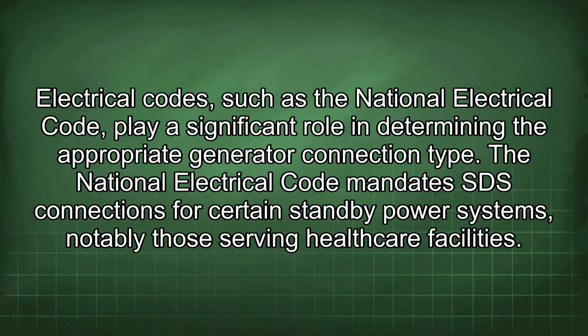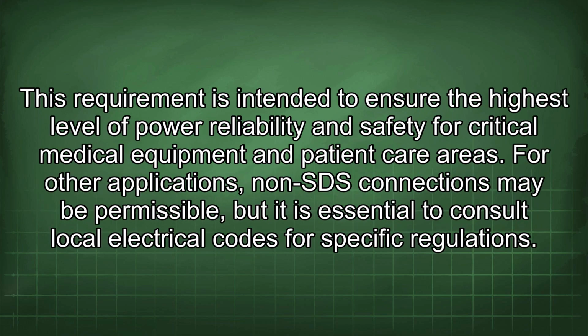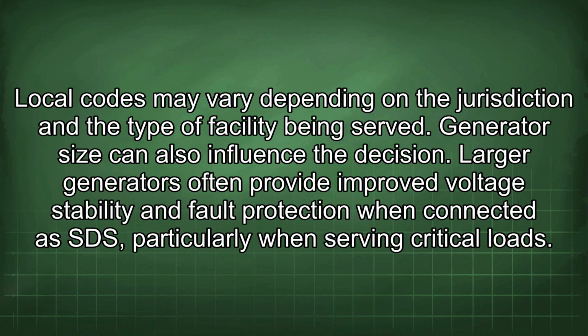Electrical codes, such as the National Electrical Code, play a significant role in determining the appropriate generator connection type. The National Electrical Code mandates SDS connections for certain standby power systems, notably those serving healthcare facilities. This requirement is intended to ensure the highest level of power reliability and safety for critical medical equipment and patient care areas. For other applications, non-SDS connections may be permissible, but it is essential to consult local electrical codes for specific regulations. Local codes may vary depending on the jurisdiction and the type of facility being served.